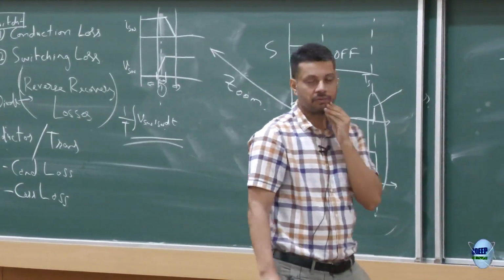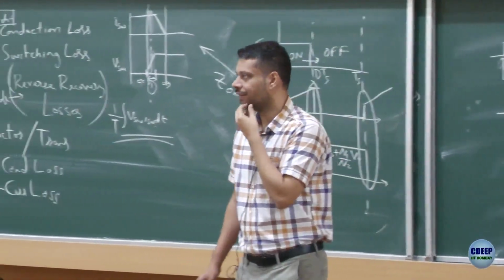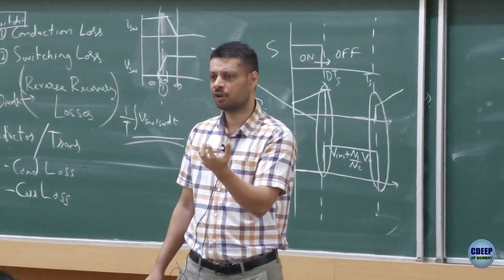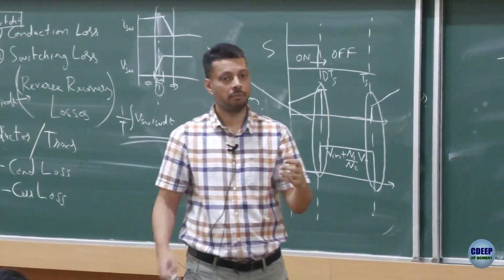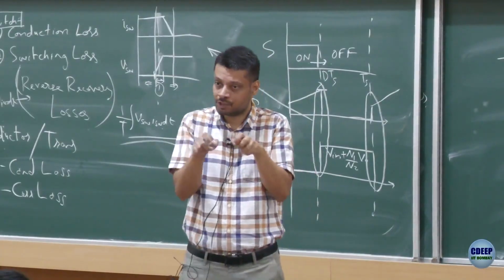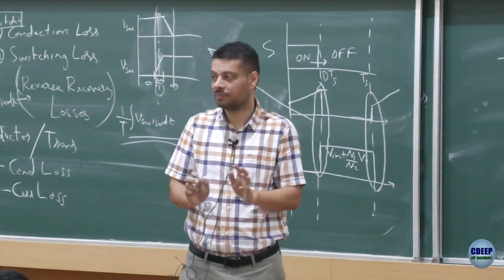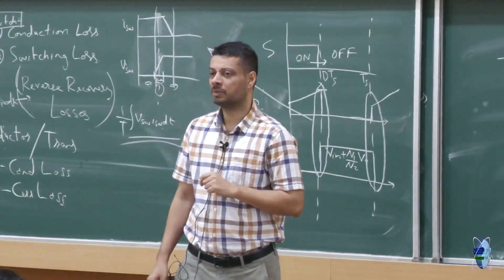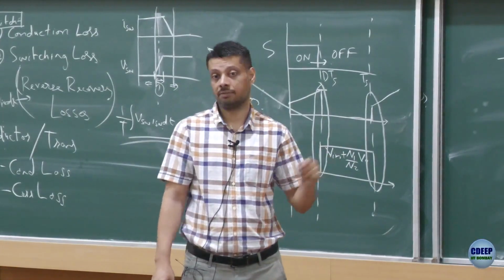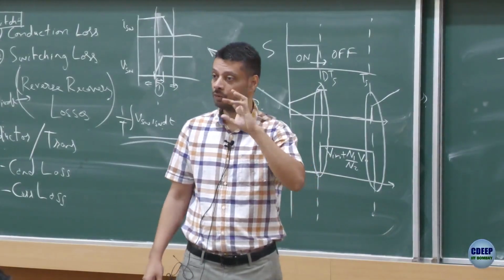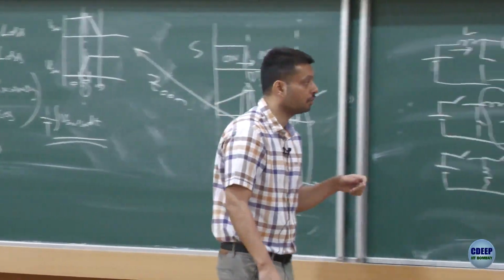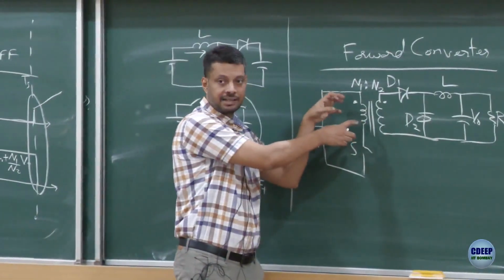Unlike flyback, flyback is actually really, really good. You would find a lot of applications around you; any electronic board you open may have a small flyback sitting somewhere. Forward is not as common a circuit, but it's very important, because this changes the whole principle of operation going from flyback, where you are using the magnetizing inductance itself.